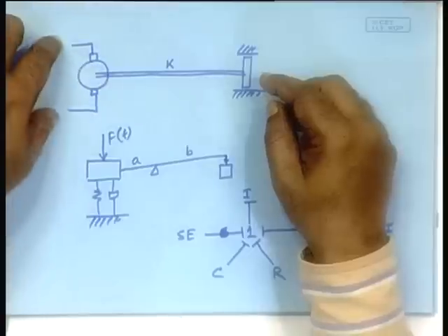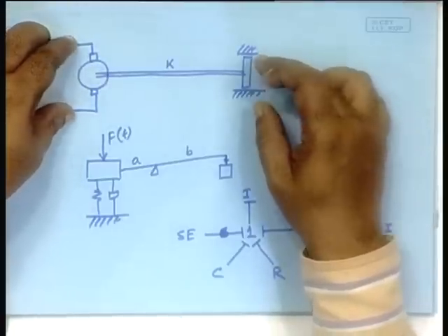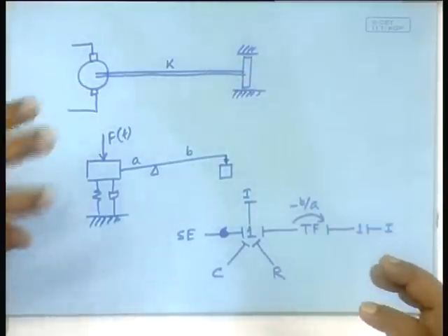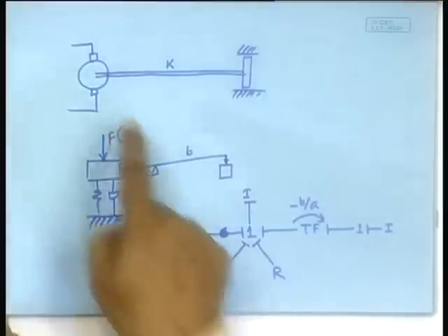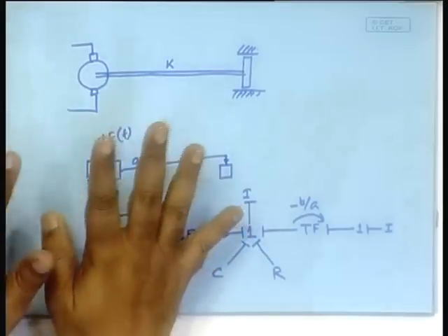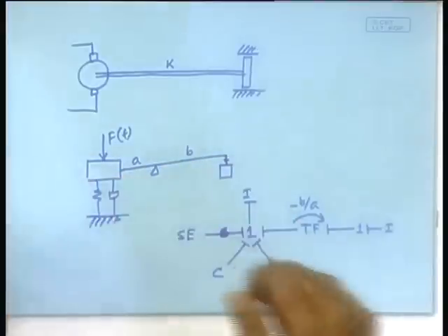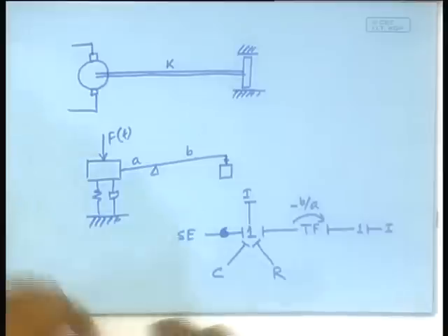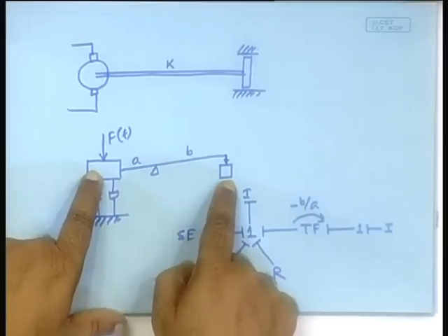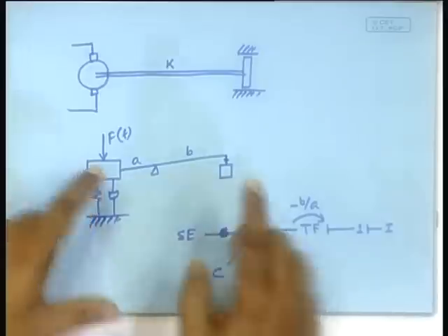which means that even though this and that or other elements in the system, for example, here there was an inductance. So, there would be these inductances and the masses would have their own characteristic frequencies, while this shaft will have a very high characteristic frequency. So, they will tend to oscillate at quite different frequencies, right. Here also, if this fellow has a very rigid shaft, that means you will assume a capacitance here, but that capacitance will be set to a very high value, as a result of which this will tend to vibrate at a very high frequency, much higher than the characteristic frequency of the other elements. What is the practical difficulty with that?